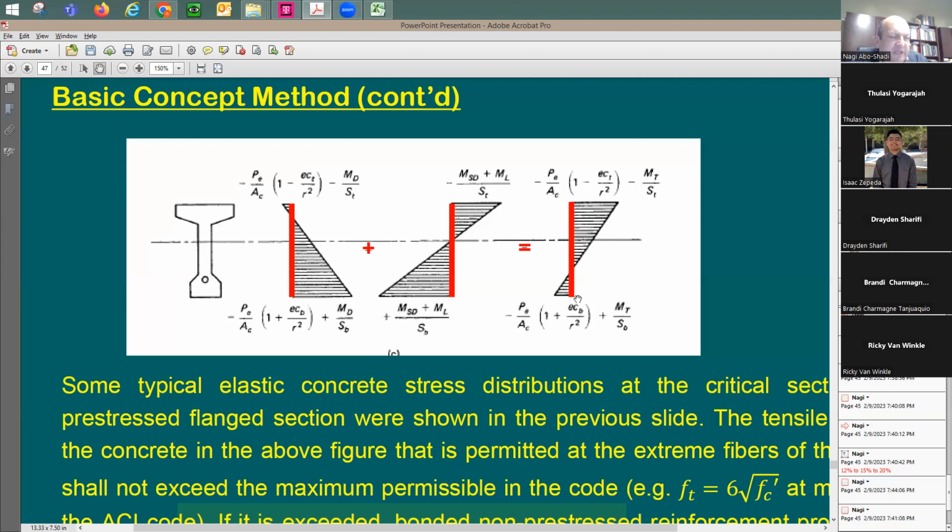If this beam here, this pre-stress beam, will have no cracks at all, let's say because the bridge that you put there is just running above a section of the ocean, and you have a harsh environment, you have lots of chlorides, lots of sulfate. So what would you do here? You'd like to reduce the amount of stress in your analysis, because when we studied the cracking point in concrete beams, we said it's going to be cracking at, if you remember, 7.5 square root of f'c.